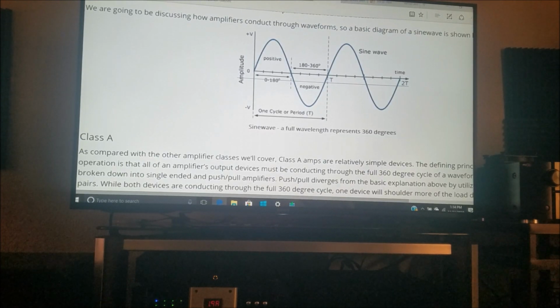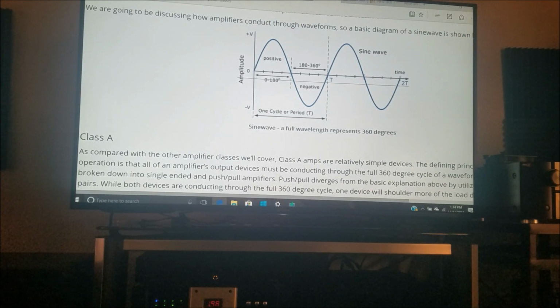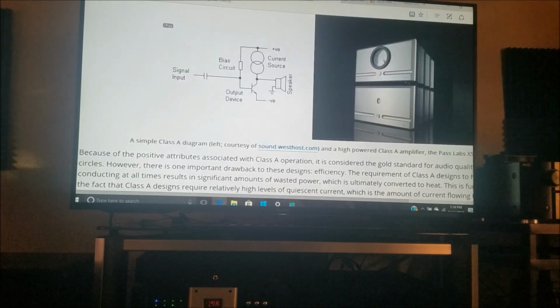The amplifying element is biased, so the device is always conducting. The quiescent collector current for transistors, and drain current for MOSFETs or vacuum tubes, is close to the most linear portion of the transconductance curve.